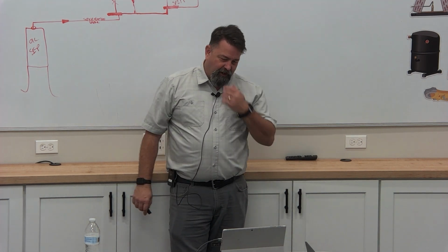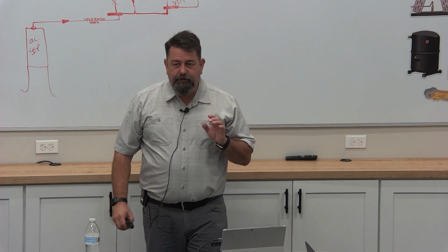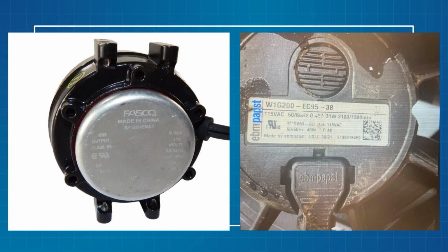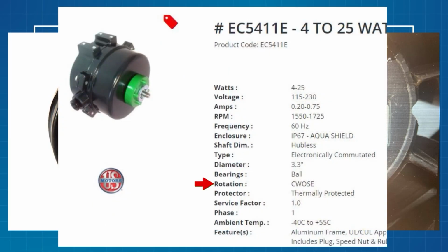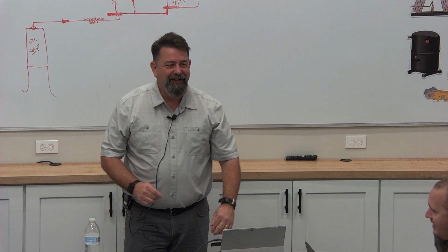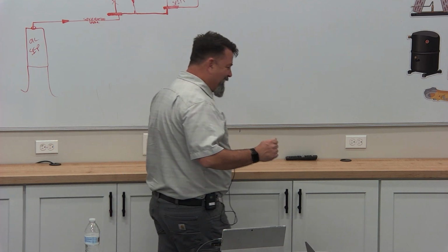Alright, so that's the way it was for years and years. Now that is changing to make things simpler, and it may have overcomplicated things a little bit. But if we look down on this one, rotation is clockwise opposite shaft end. So that's why I'm like, we were saying that motors always rotate backwards, because it's from the shaft.